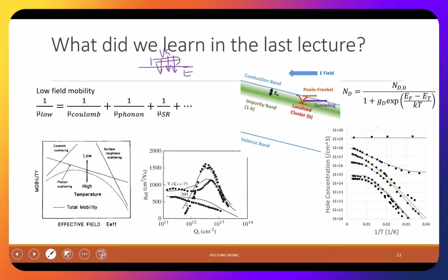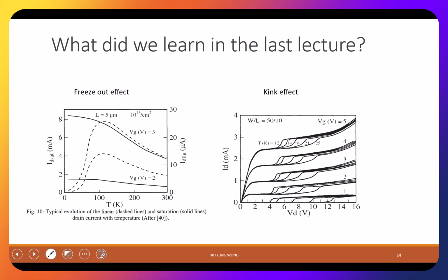At room temperature, we don't feel it. Then we say, okay, all the dopant, right, boron, arsenic, they all ionize. They become free. They have free electrons, but at low temperature, they just stay trapped there. Okay. We also learn about the freeze-out effect. When you have a very low temperature, all the dopant supposed to be conductive actually are not conductive at low temperature. Again, just the same as what we said earlier, because they cannot get ionized.